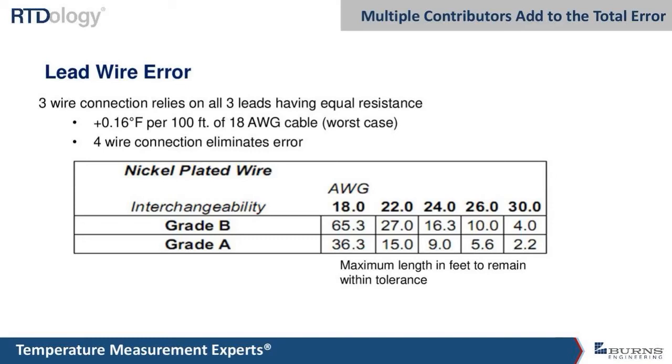In one of the videos I've done on accuracy, I have an example of someone trying to measure room air temperature with probes that were sticking down from the ceiling. They started out with a 3.5 inch, 1/4 inch diameter probe, which seemed like a good selection. And it turned out that above the ceiling, it was about 95 degrees Fahrenheit, and in the room, they had it controlled to about 70.